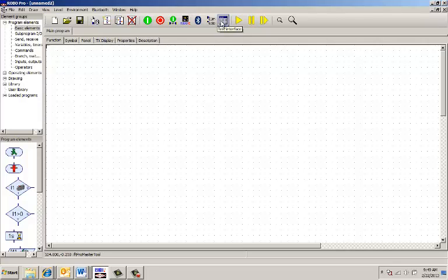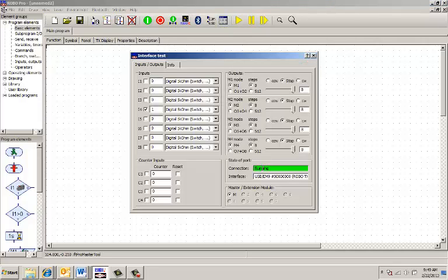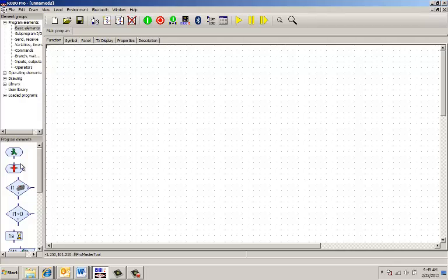So let's verify first that I'm connected to my interface, and I am, and I have my sensor connected to port I4. So I'm going to change that to analog 5 kilo ohm, because remember I'm using a photo resistor there. Alright, and as usual I'm going to start my program with the start icon. Now before, we used 2 analog branches to make our decisions. However, once you're in the higher levels, you have access to a lot of more sophisticated displays and those kinds of things. So let me show you instead how to